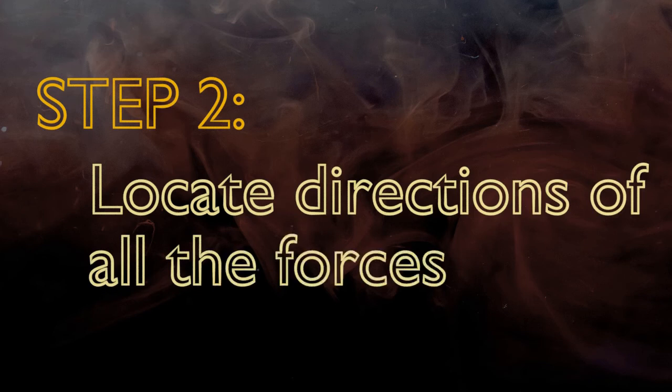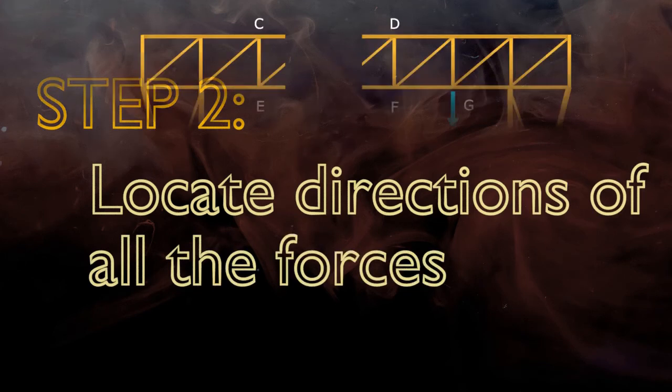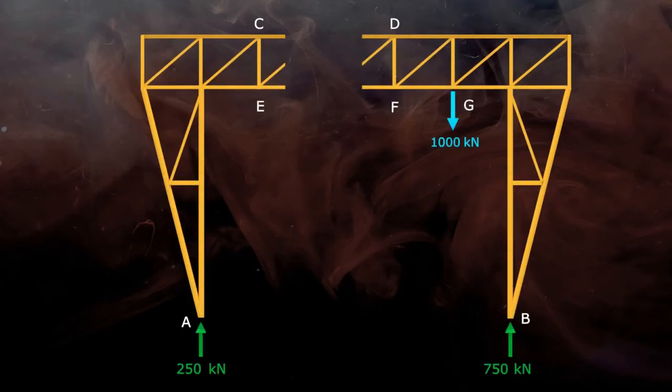Next we have to locate forces at all the cut members, assuming that these are the internal forces acting in the members. The force can either be tensile or compressive. Let's assume that all the forces are tensile. Name the forces like FCD, FEF, etc., writing the nearest joint first and then the joint at the other end of the member.